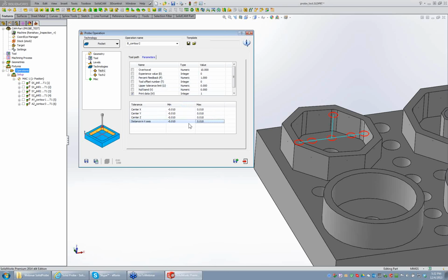different cycles with different options. One cycle can show you on the screen on the machine, as the Heidenhain does. You will get a report on the screen. Other cycles for other probe devices will save the results of the measurement in a file, in the controller or a flash card.